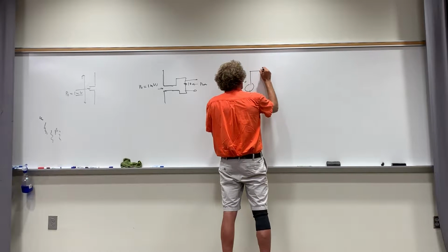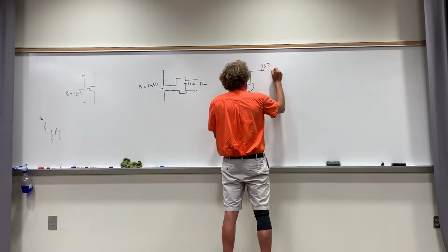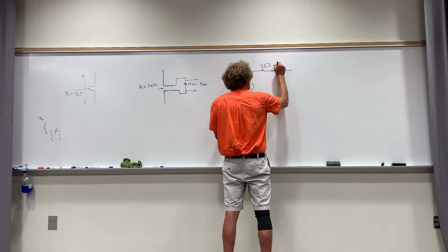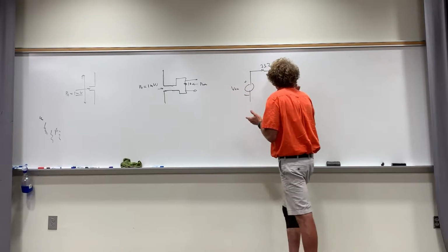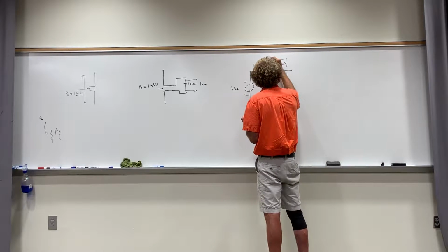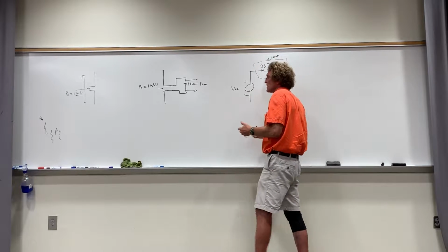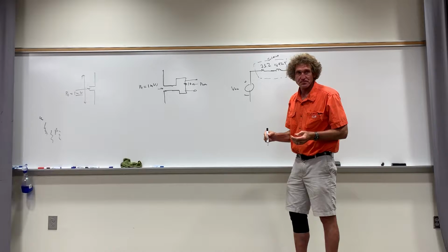Well, the impedance is going to be equal to, if it's the half-wave, 73.2 ohms plus j42.5 ohms. Now that is internal. All this is internal. So it would be something that would be related to the actual wire itself of the antenna.